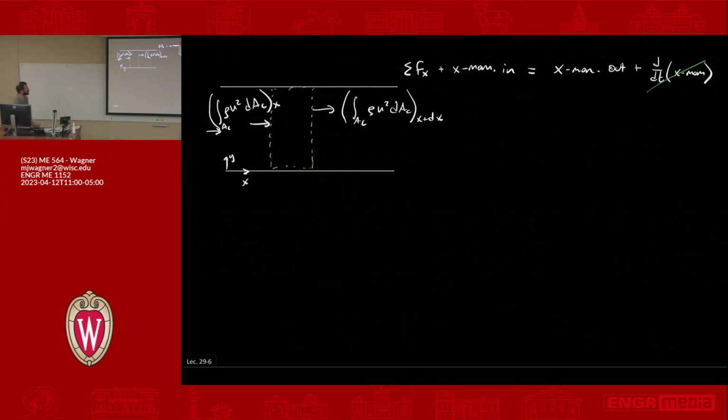We also have pressure. The pressure is changing as a function of position here. So pressure would be P times A c at x. Leaving, let's draw it, we usually draw pressures both going in, so on the other side it would be P A c at x plus dx. So pressure here, pressure here. What else are we missing? We said there's no change in time.